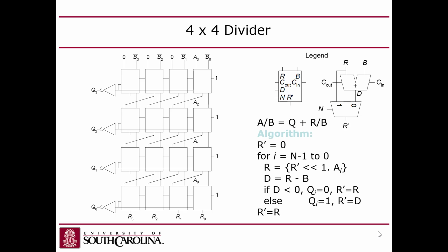Yes? You could also have extended diff to 33 bits instead of 32, and then you get the extra bit. I put it in my write-up. Well, diff was 33 bits, that's how we captured this. You added 32 and that truncated, and then you extended. You have to extend first and then add. Oh, okay. You never truncate. Okay, I never tried that. It worked?